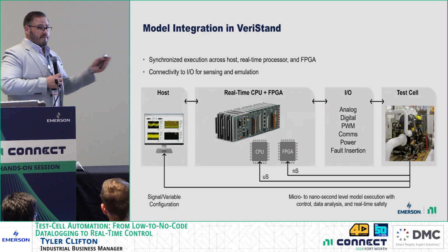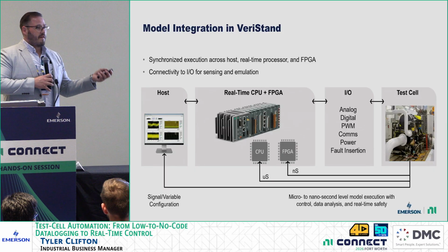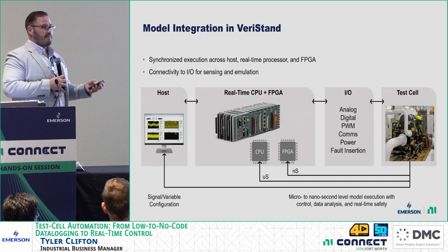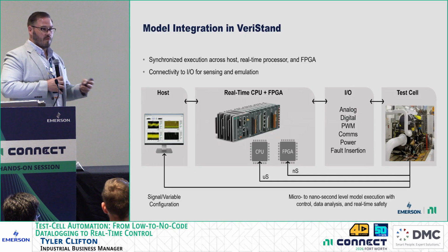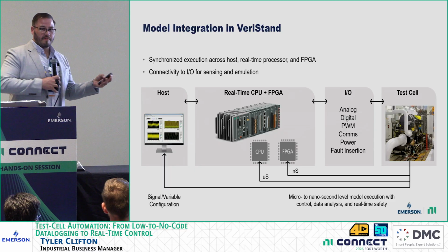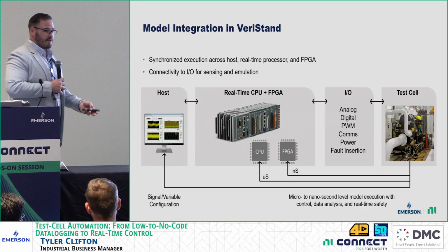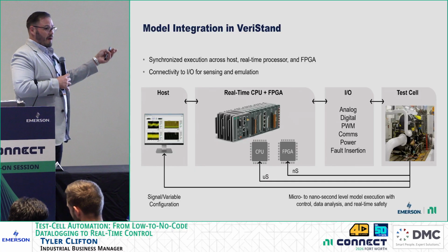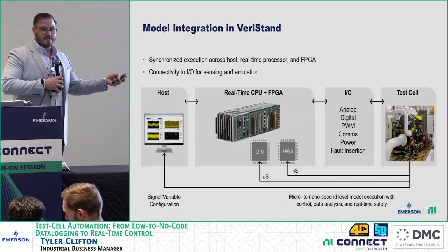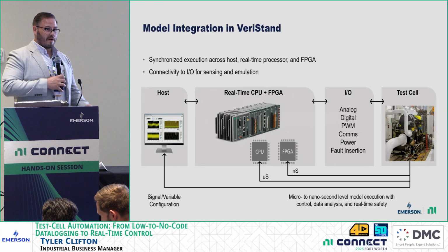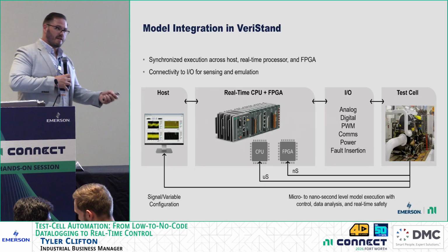Let's talk about what model integration looks like. So VeriStand takes in models that follow the FMI 2.0 or 3.0 standard. Basically, a model that exports as an FMU, right? So any software that makes an FMU, by the way, if you don't have software that makes an FMU, LabVIEW can make an FMU. And if you need a model to be emulating components of your system, it's a matter of deciding what kind of response rate do you need from that model to emulate the missing components in your system level test.